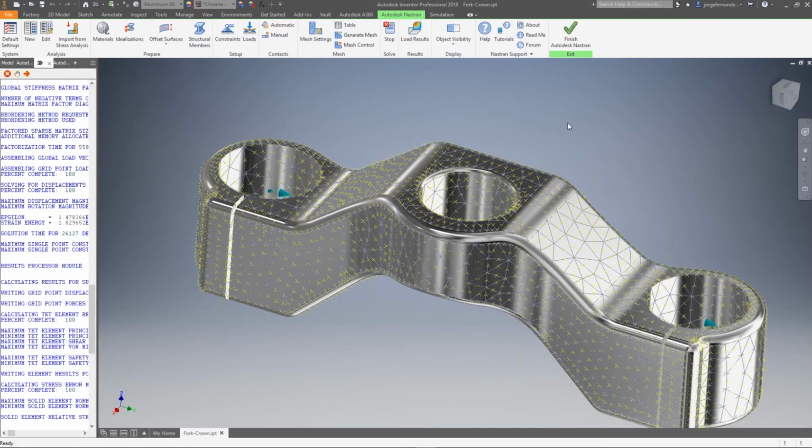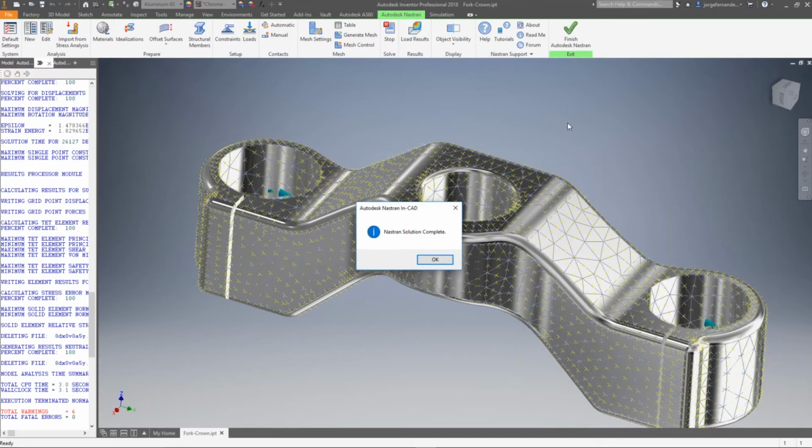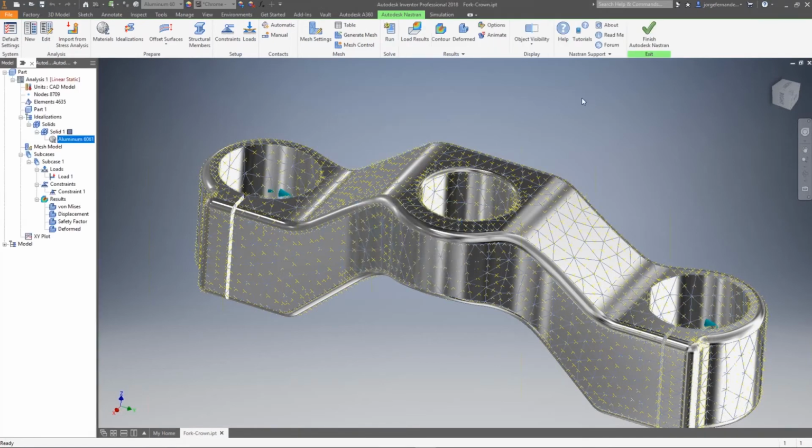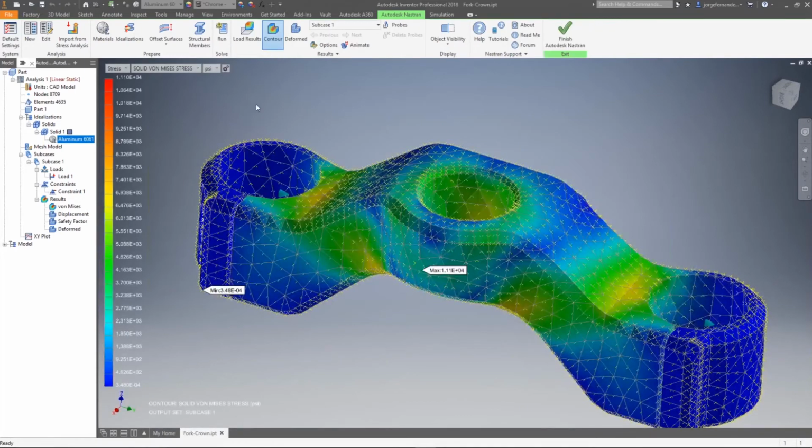So we literally looked up beforehand before we got on here. We verified again today, and the maximum yield strength was 40,000 psi. We came up with something like that, right, Nigel? Yeah. So knowing that, we'll take a look at the contours here and be able to decide on our own, is this part gonna be okay or not? And so we go to stress, solid von Mises. We see that the maximum here is definitely under 40,000, right?